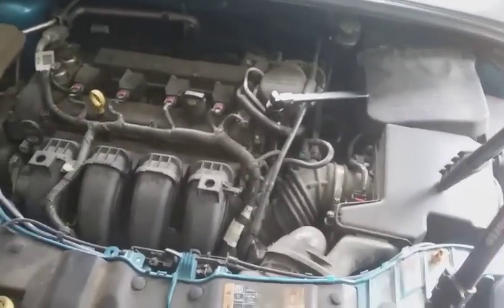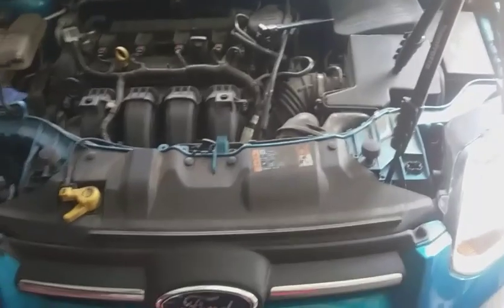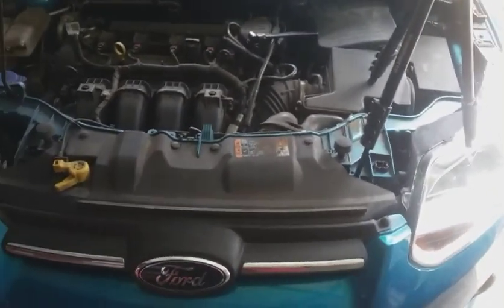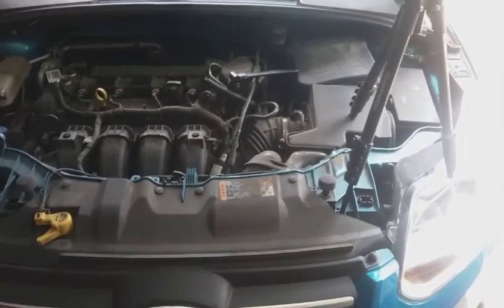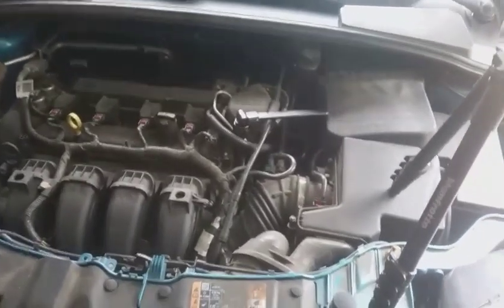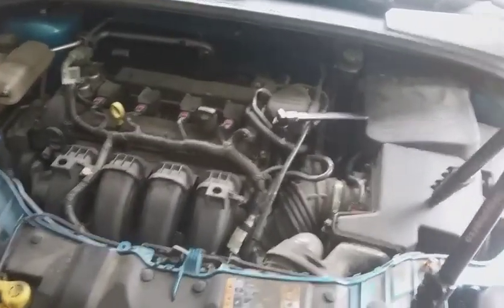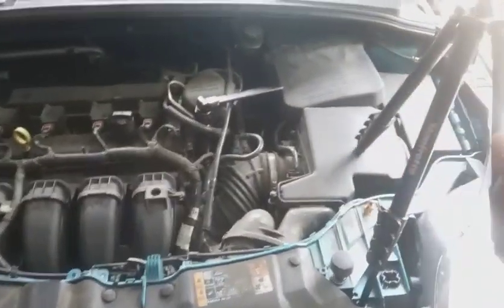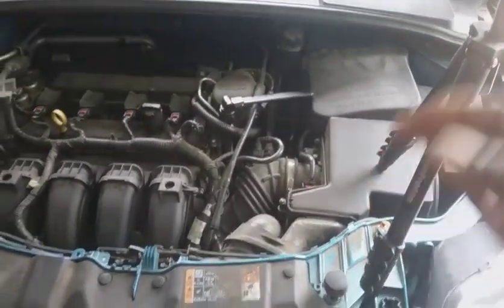And if anybody knows, when you put gas in the car and fill it up, put the cap back on, start it up, and it barely wants to start. Sometimes you start it up in the morning and you drive and it'll stall intermittently, run funny in some cases. Those are going to be vent valve symptoms normally. And what happens is the vent valve is getting stuck open.